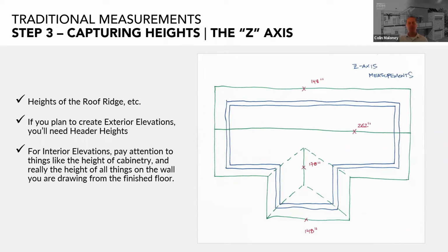That sketch of the roof is basically showing what a zip level sketch to get heights would look like. You got your measurement on the eave and your measurement at the ridge. And as long as you know the X by Y measurements of that roof, that's all you're going to need to construct it. It's the same as I was discussing, I believe, with Barry earlier, that getting the degree measurement and the X by Y measurements will also help you produce the pitch and the height information as well. But the zip level is a little more definite.